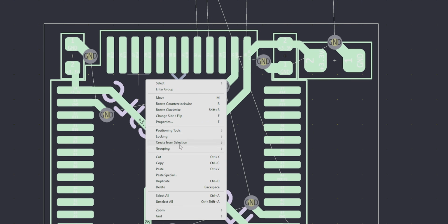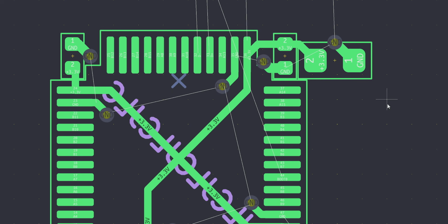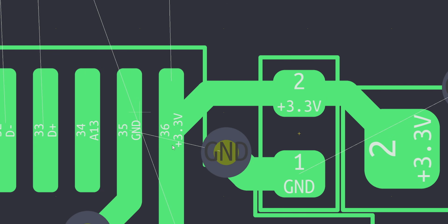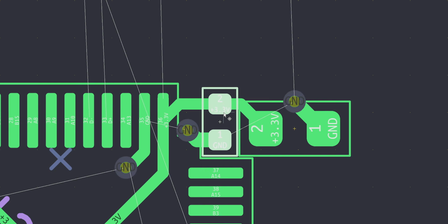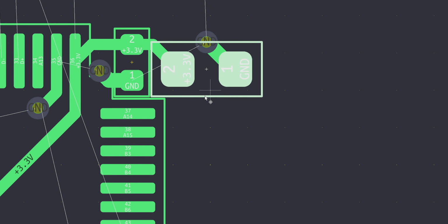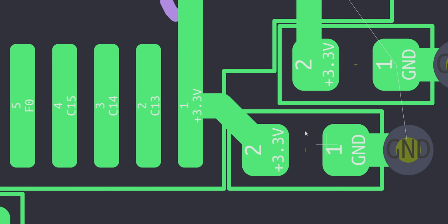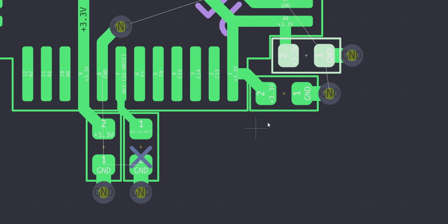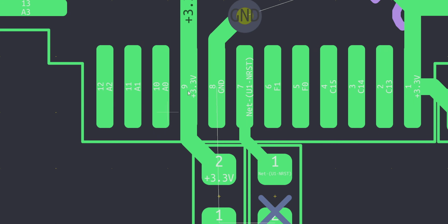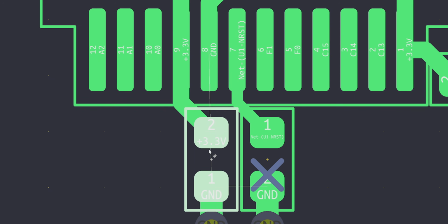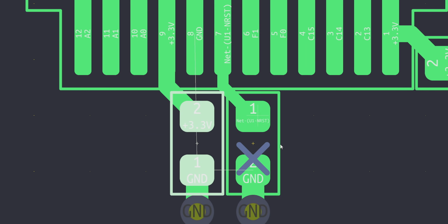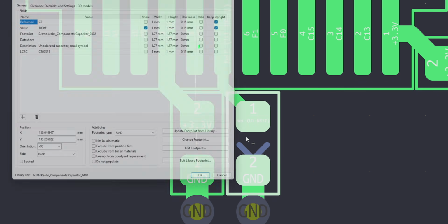So you see if I right click, I just degroup this real quick. I can start pinpointing this. We have our 3v3 pin here. That's feeding into a decoupling capacitor. We have our bulk decoupling right here. Same thing down here. We have another 3v3. We have a 3v3, all feeding into these 3v3 decoupling capacitors. Same down here, another one feeding in there. So this is a 3v3 pin. This is our reset pin feeding into that. I believe it's a capacitor on this.